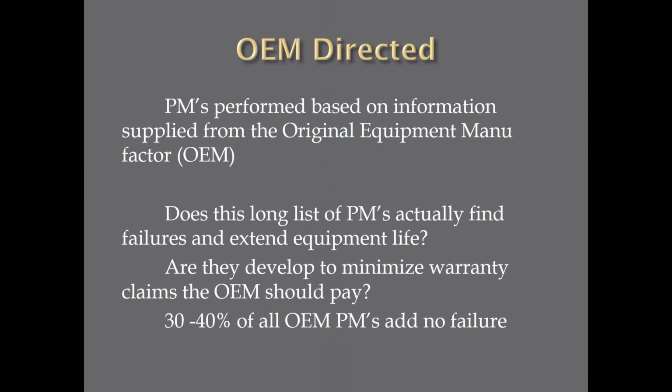Now we have these OEM directed PMs. These are PMs performed based on information supplied from your original equipment manufacturer. And a lot of you know when you look in the back of that book, there's a whole list of PMs you're supposed to do. But how many of those PMs actually find failures? How many of those PMs actually extend the equipment life? You know, are these PMs just developed to minimize warranty claims by the OEM?